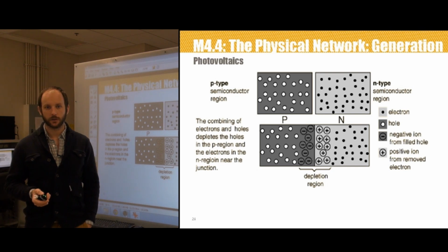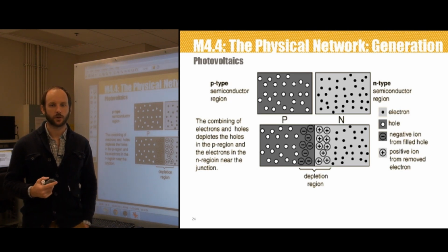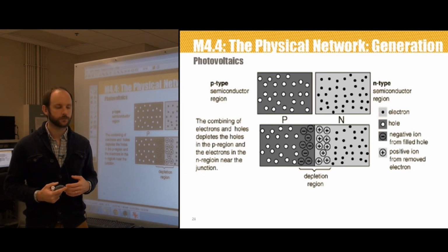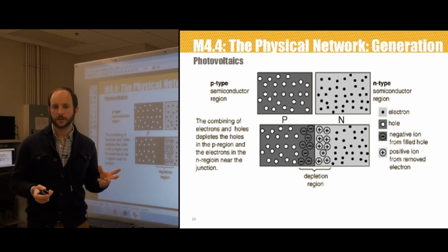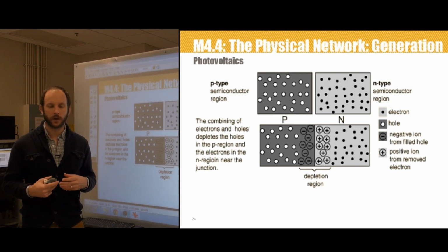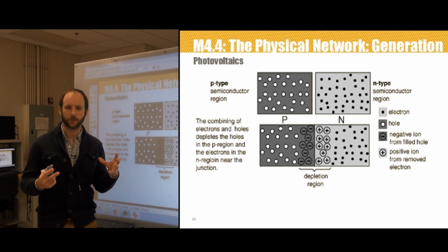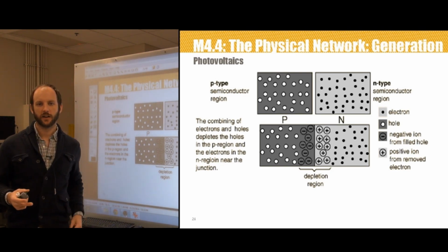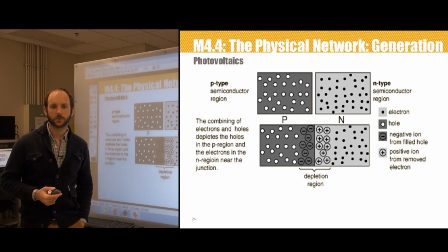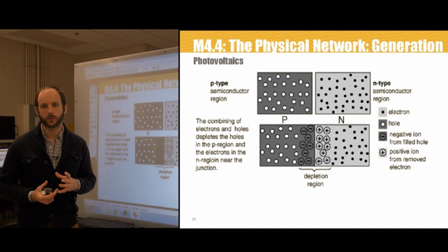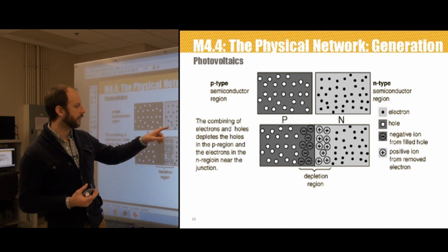In an N-type material, a small amount of phosphorus is added to the semiconductor, such as silicon, via a process called diffusion or implantation. So we've got a normal piece of silicon. We then somehow inject phosphorus into it. How that's done is not too important. You just have to accept that phosphorus now exists inside the silicon. After the phosphorus bonds with the silicon, we're going to result in a material that has freely available